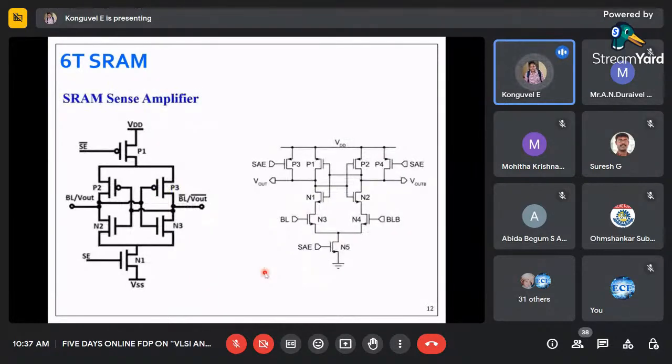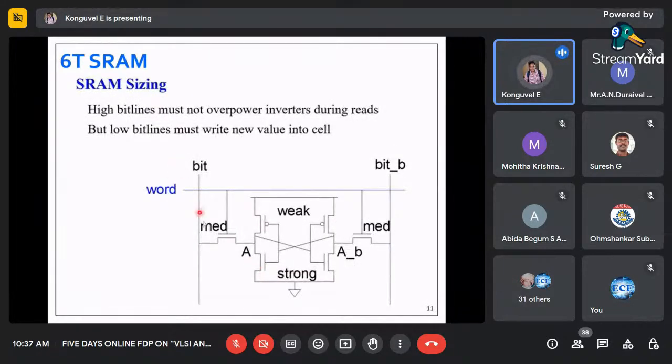So as I said, the other important part of this 6T RAM is the sense amplifier. Here we are having a weak, hanging signal during the read operation. During the write operation, we don't care because we are energizing the cell to store whatever value we are giving in the bit and bit bar lines in A and A bar respectively. But the read operation is not like that.